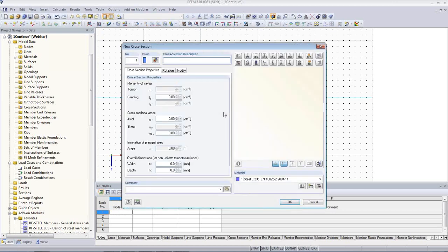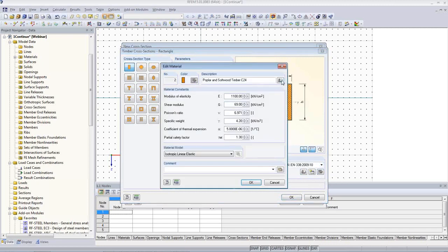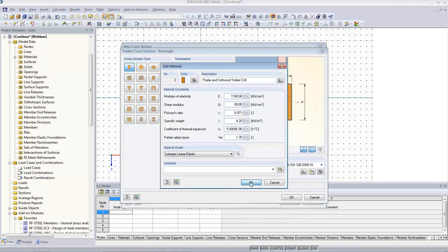I want to create a cross-section, so I can choose here from the cross-section type, rectangle, and we say here 300 millimeters by 500 maybe. And also I'll choose from materials that I have here. Some is already prepared here. You can change it, go wherever you want to, and use whatever type of material you have. It comes all with the software. Okay.